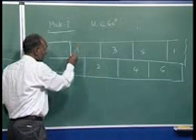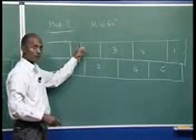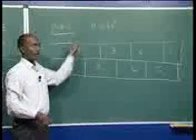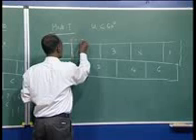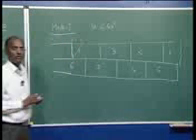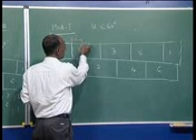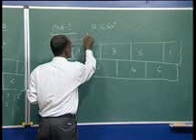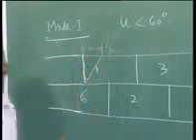There is some period of delay, meaning the valve is going off and taking some degrees; that is the overlap angle, and this is your angle u. So the remaining period here will be 60 minus u.